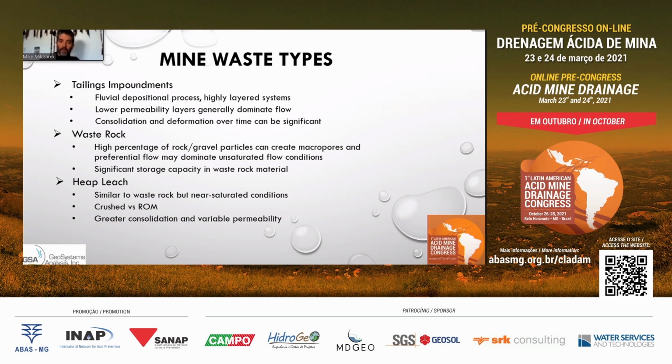And this will affect how, if you put an ET cover system on it, the flow occurs and how water goes into the mine waste. And the other thing to consider with tailings is you will have consolidation and deformation over time as the tailings